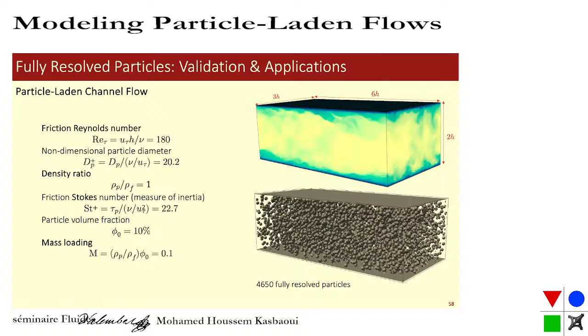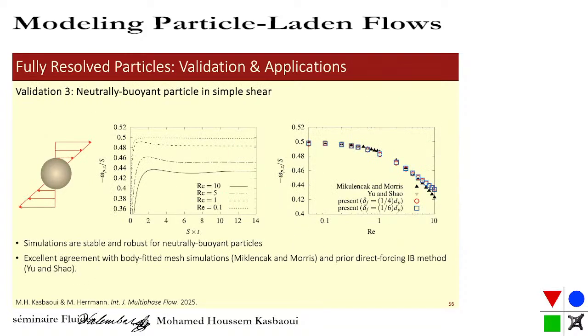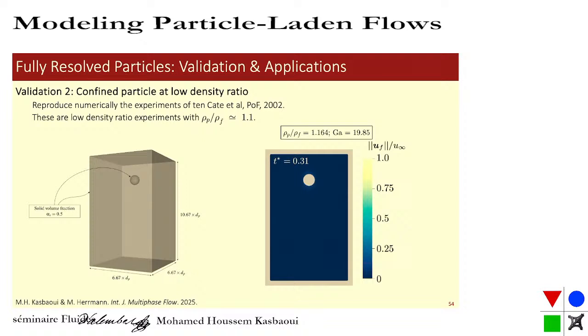So you're saying I should drop turbulence, go to a laminar flow, and then compare with an analytical solution. I mean, we did a lot of that in the context of these simple validations, laminar solutions, and so on. You're saying I should do Couette flow with convergence. Okay. Linear velocity profile, and see if it works. Because I can tell you the relaxation method does not converge. It has an error that can be as low as 1%, smaller, but it does not converge to the right solution.